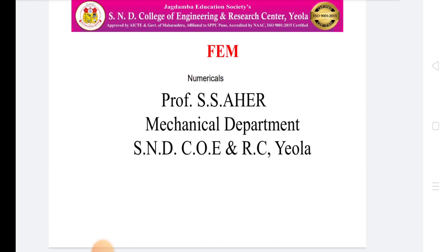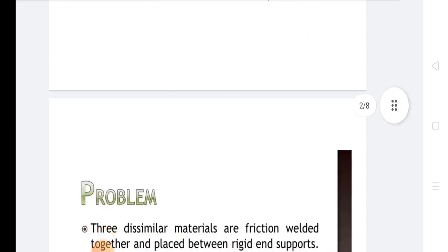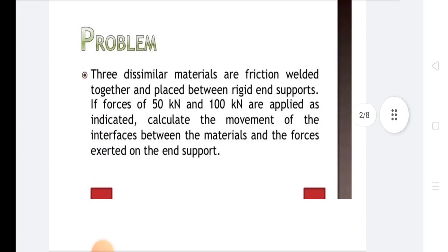In step 1, discretization of the given continuum, the first step in FEM is to divide the given continuum into small regions called finite elements. The analysis is carried out for each of these elements. The points where properties are to be determined for an element are called nodes. The process of discretization of the continuum is simple.